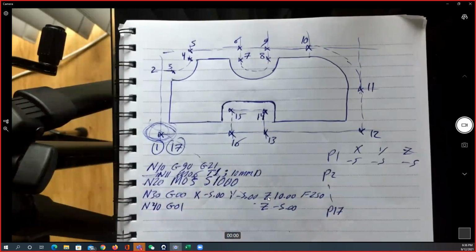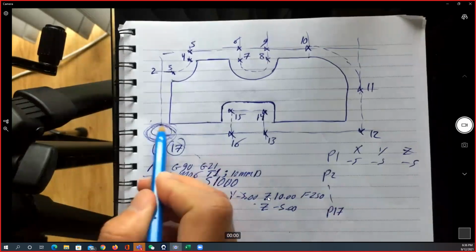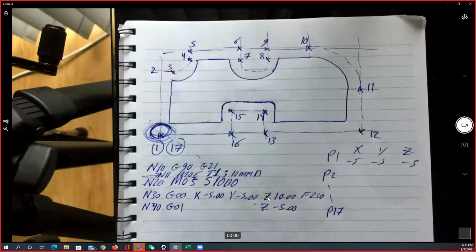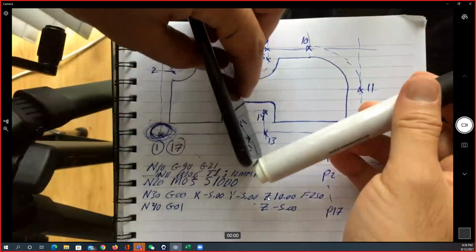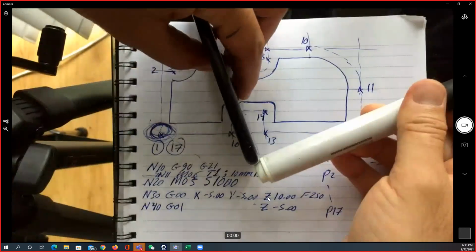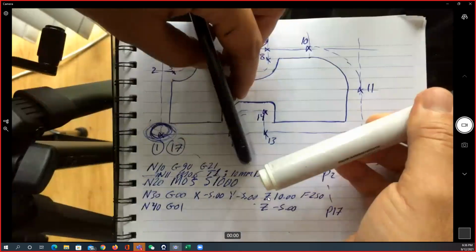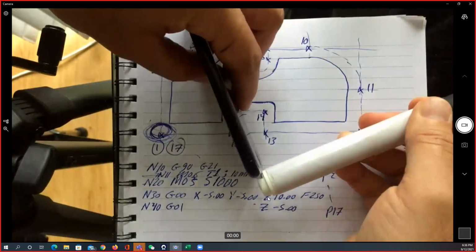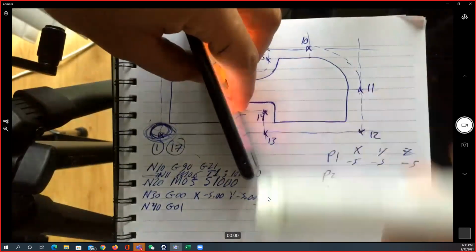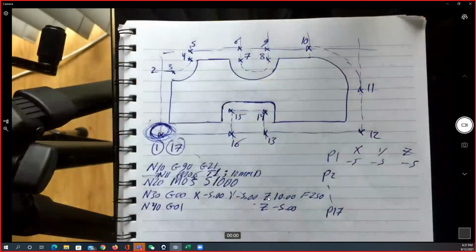Now, my cutting tool is in position. To explain that much further, let's say that this is my part, and from the side, that's what will happen. My cutting tool is going inside by 5 millimeter depth. So the side of the cutting tool is what cuts the side of the work part, where it's going to move around and do the profile cutting. Is that clear for you guys? I'm going to show you that.